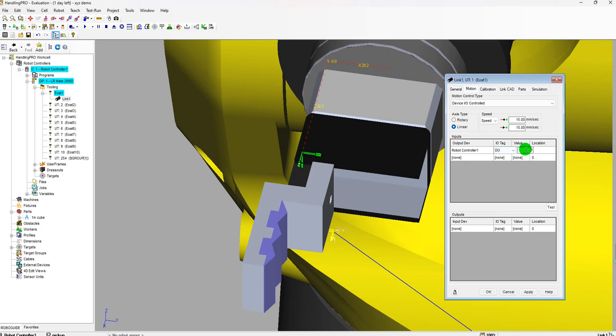And the value here is the number of this output pin, right? So you can use any pin that hasn't been occupied. I will, for example, use 2. Okay, so let's see. Then you change when it's going to our location, it's on or off, right? So it's logic. So let's make it on.